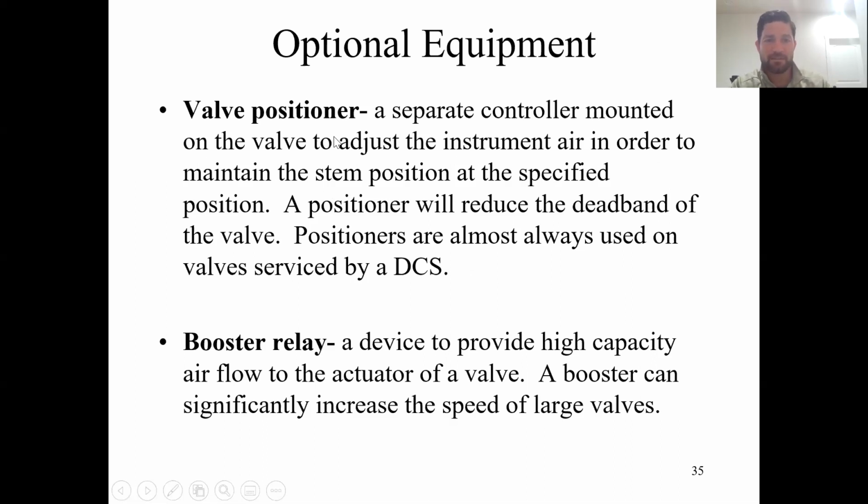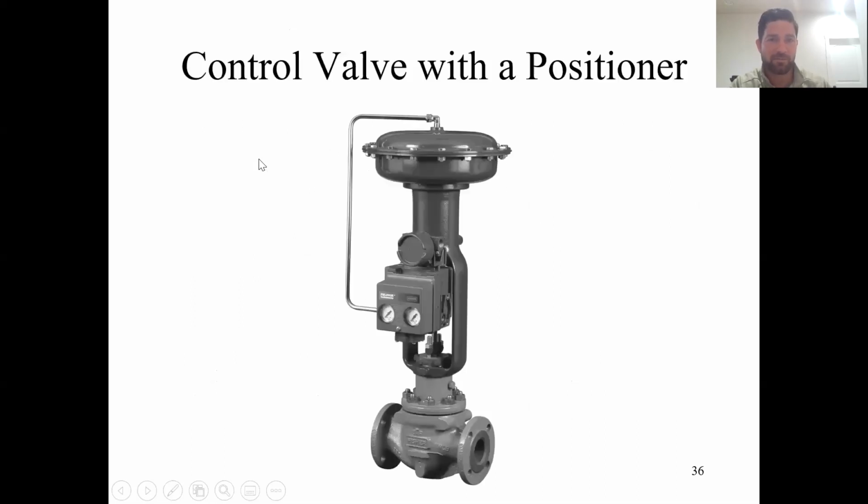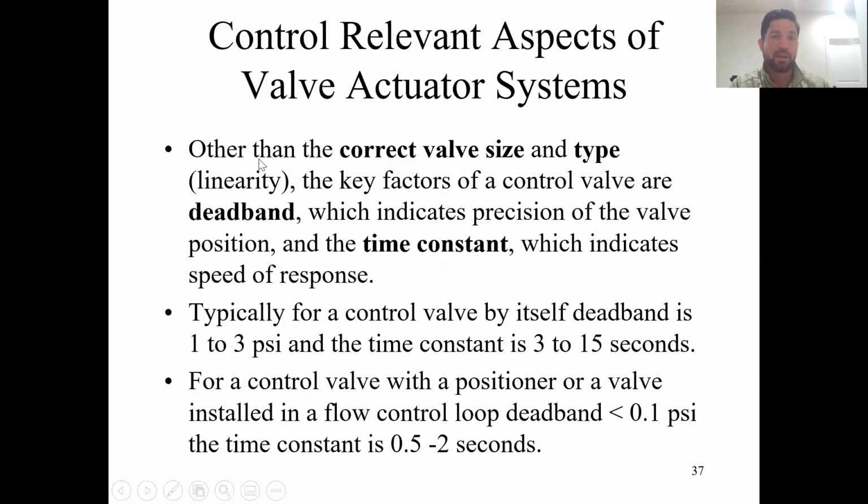In order to minimize deadband, sometimes valves have what's called a valve positioner. It's important to know whether or not your valve has these characteristics, because if it does, it's going to affect the performance of the valve, which we'll use later when we talk about how we set our PID controller settings. So some of these things now are just more about being familiar with them. Okay, and I'm going to go through these a little bit. When it comes to troubleshooting, it's useful to know the general performance.